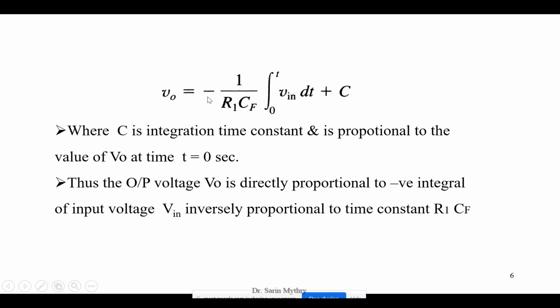We are having a negative sign, right? The output voltage is directly proportional to the negative integral of what? The input voltage, and inversely proportional to the time constant R1 and CF. So this is what is meant by an integrator and how your integrator will be working.